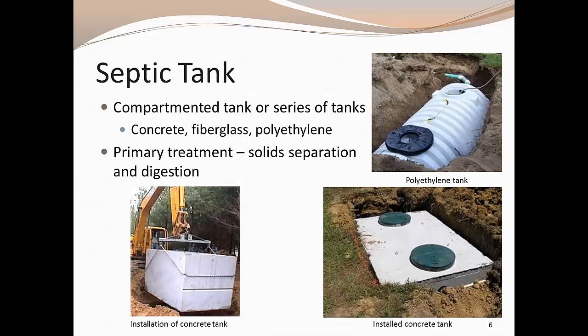Septic tanks are buried watertight containers located near a dwelling. They can be made of concrete, fiberglass, or polyethylene. Due to durability and lower costs, concrete tanks are the most commonly used in residential on-site systems. Polyethylene tanks are among the least expensive septic tanks, but have issues maintaining structural integrity under the weight of saturated soil. In recent years, advances have been made to the construction and material of polyethylene tanks. With the ribbed design seen in the upper right picture, polyethylene tanks are becoming a more viable solution.